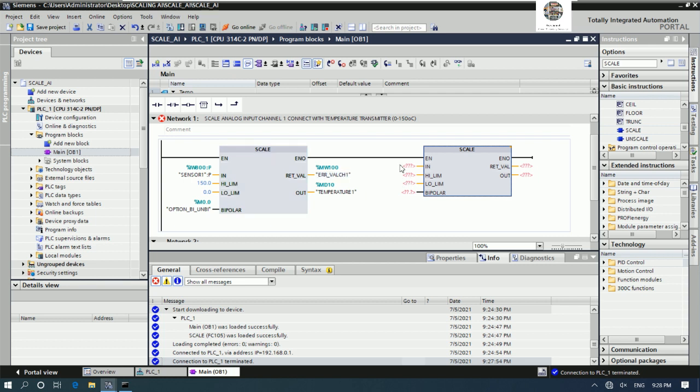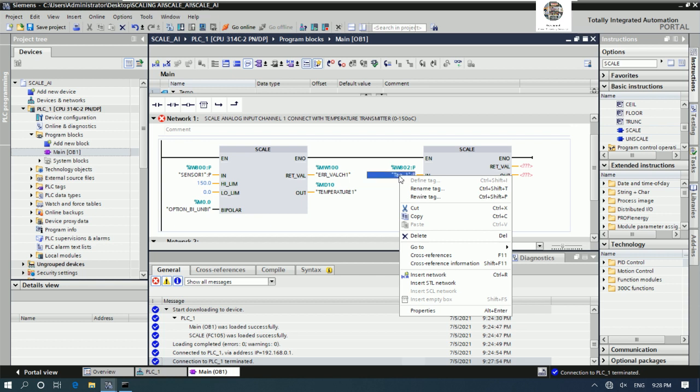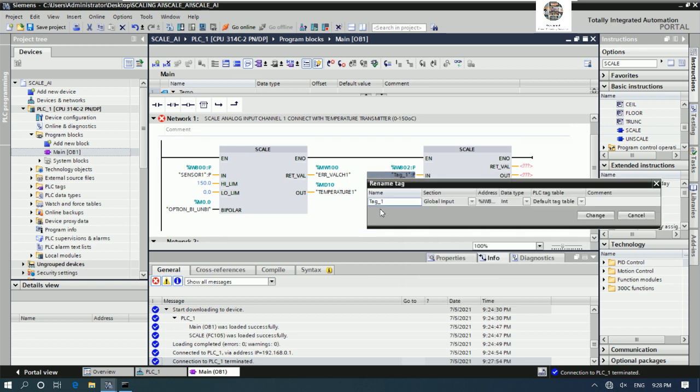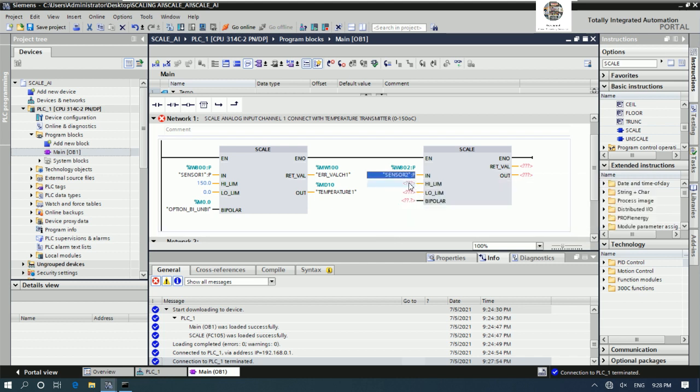Okay, so this one should be a PROFIBUS-DP, right? It is the channel number 2, or we can write command sensor 2. And example scale, high scale from 0 to 100 degrees Celsius or 100 bar.